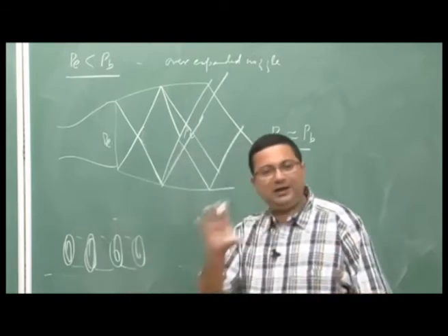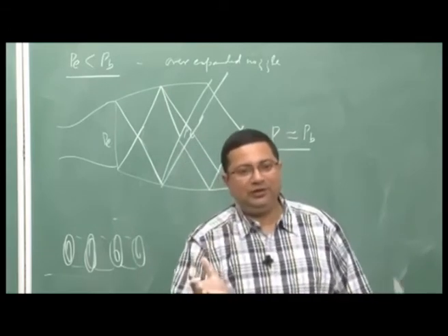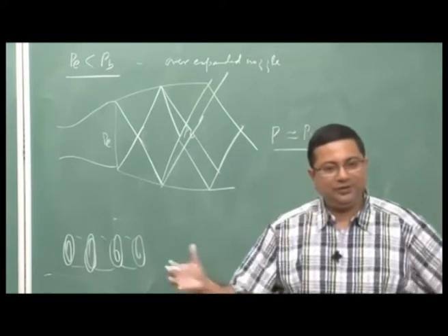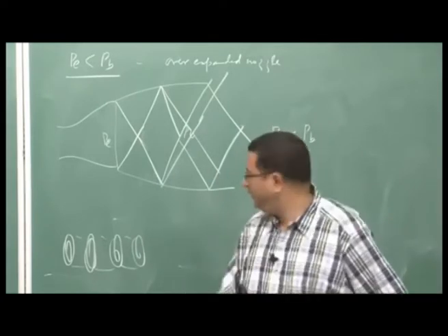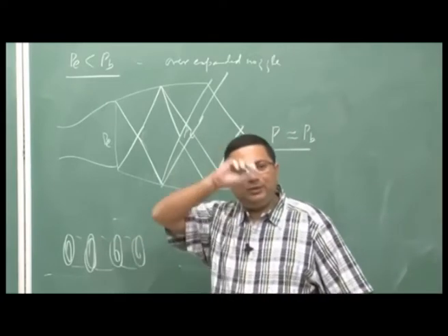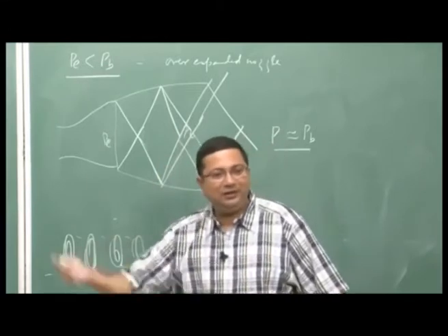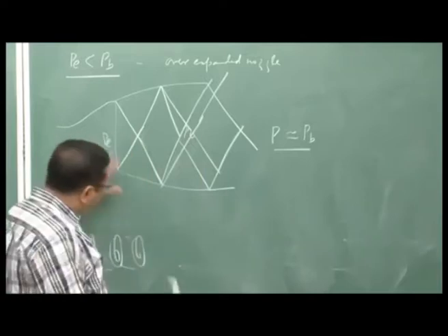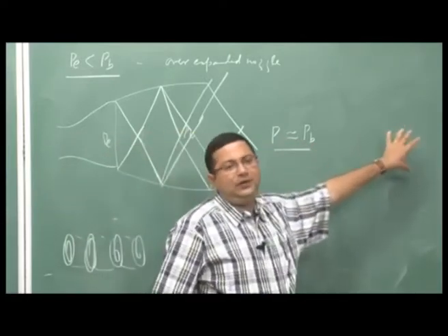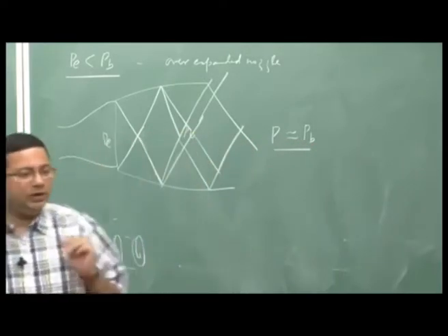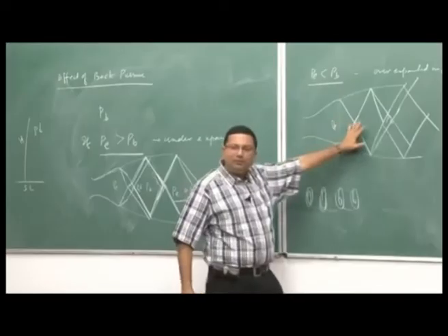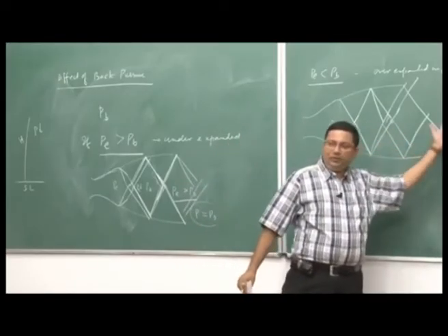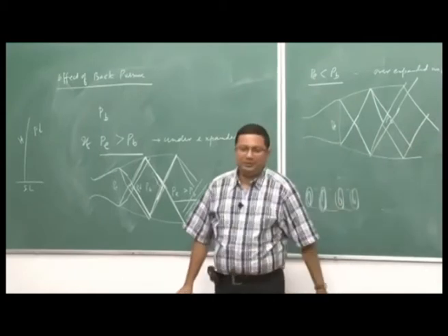There are some bright regions after the shock wave, because the flow velocity is low, you can see a lot of light there, then light like that. So, it will be like rings, the plume is like rings, this is because of this formation, okay, and it continues for a while till it finally reaches the back pressure. So, the bottom line is that at the exit we do not have the back pressure, it will not be experiencing the back pressure, some other pressure, right.